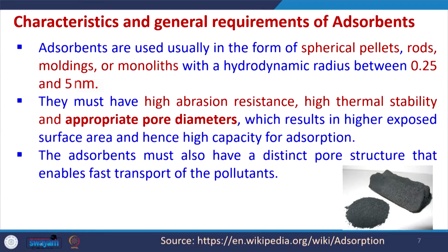Now, in addition to abrasion resistance and thermal stability, appropriate pore diameter is very important, and if we have appropriate pore diameter, it will result in highly exposed surface area and hence high capacity of adsorption. So, what is the appropriate pore diameter? I will just give you an example.